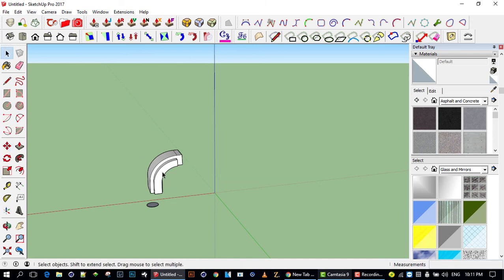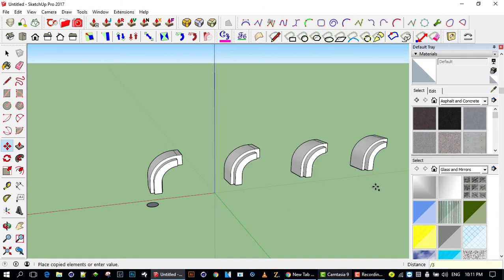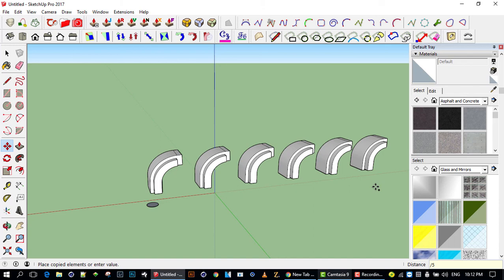Or what I could do is take that one, press M, Control to create an additional one, move it to an area, and I say that's the start and the end point, and I'll say divided by 3, and we'll put in 3 extra units. Say divided by 5, it will put in 5 extra units, equal distance between the first one and the one that I dragged out. So that's the move tool, the M, that I use.